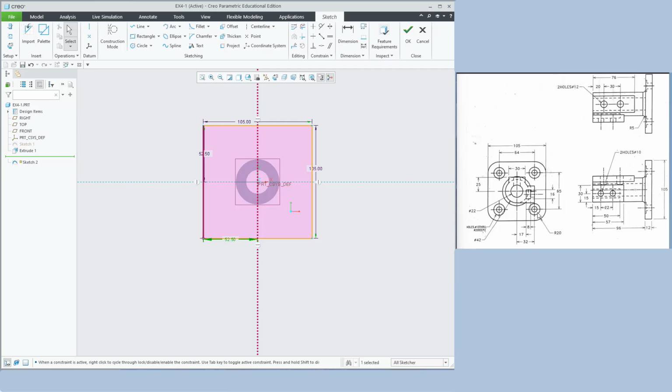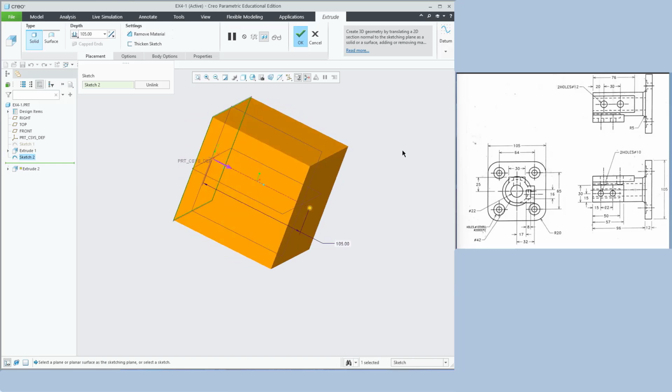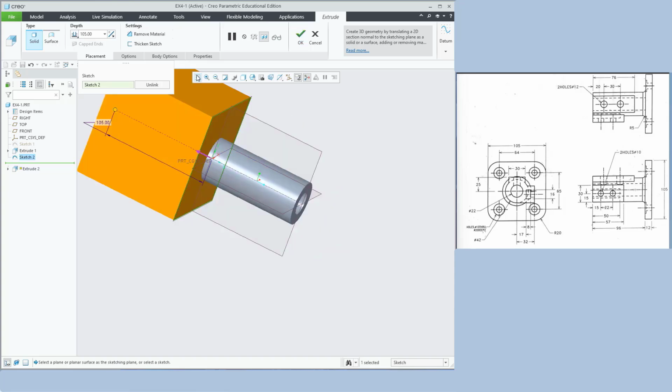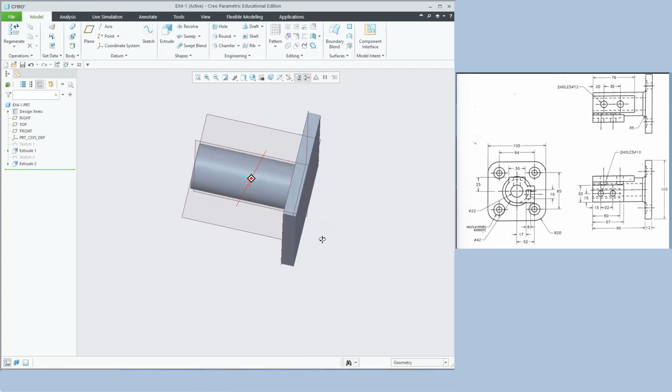Don't go to the fillet and all those things, just try to do it simply. Extrude. Now this extrude distance is required. So we are going to extrude it. Change the direction. We are going to extrude it for only how much? 12. It is like this. Finish it. The base thing you got is over.